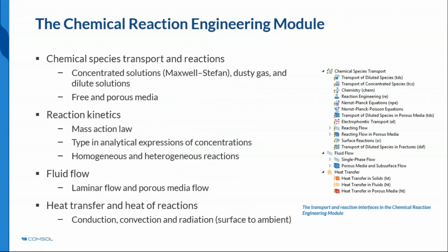The transport interfaces take a homogeneous approach to modeling the transport of species, and these use correction factors such as the Bruggemann correlation to account for the influence of porosity on the effective diffusion coefficient. Within COMSOL, reaction kinetics can be described automatically using the predefined mass action law or through the input of your own analytic expressions based on concentration. The CRE module can also be coupled with the fluid flow interfaces and the heat transfer interfaces to couple these to your chemical reactions.